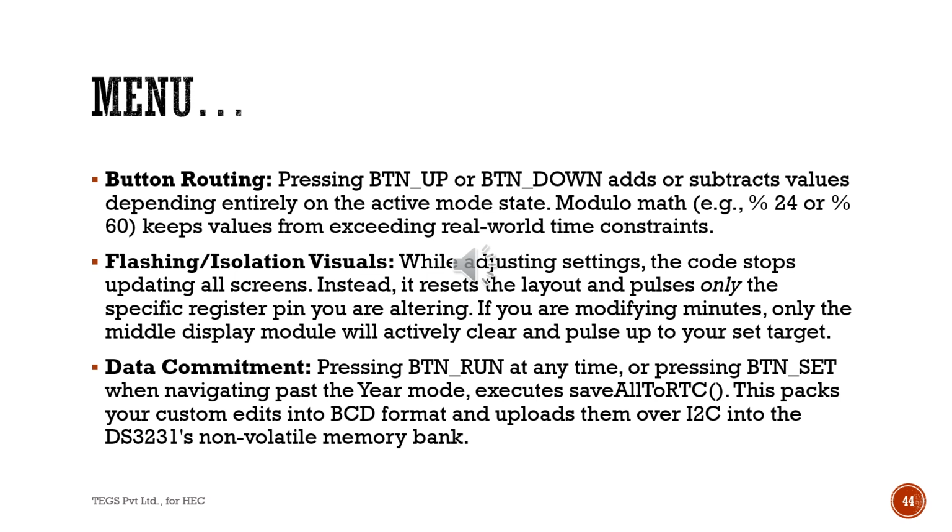Flashing and isolation visuals. While adjusting settings, the code stops updating all the screens. Instead, it resets the layout and pulses only the specific register pin you are altering. If you are modifying minutes, only the middle display module will actively clear and pulse up to your set target.